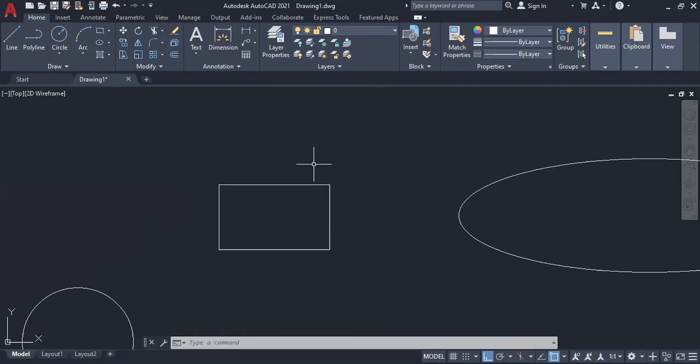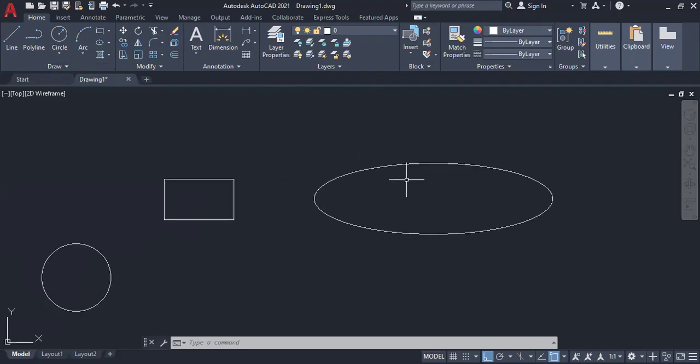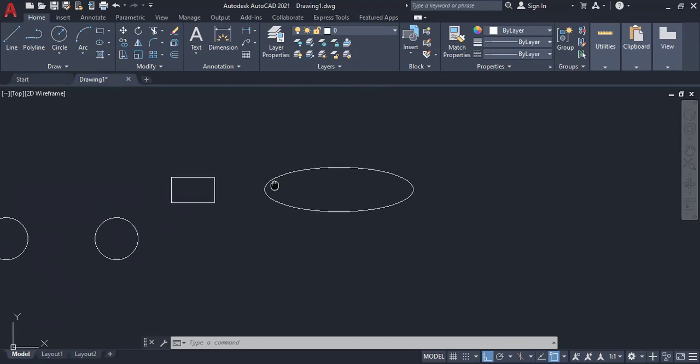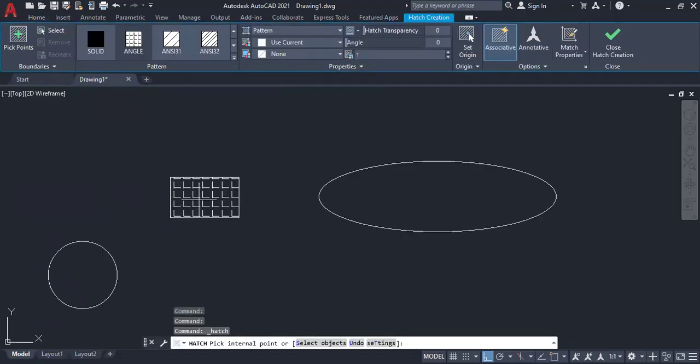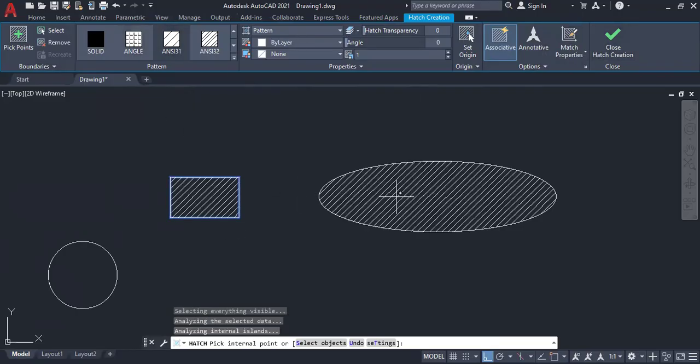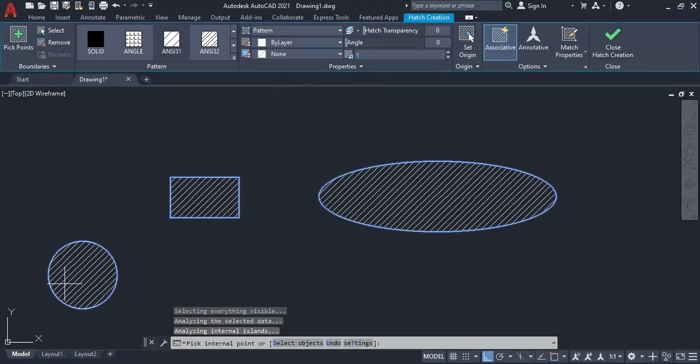How you can create the small shapes, the easy simple shapes, in AutoCAD drafting. Okay. Now I'll go to the hatch. So when I'm clicking HS, a different ribbon bar will open. There you can select which type of hatch you want. You can give the hatching, and you can give the distance and angle also. If you give one or two, it will increase the hatch.